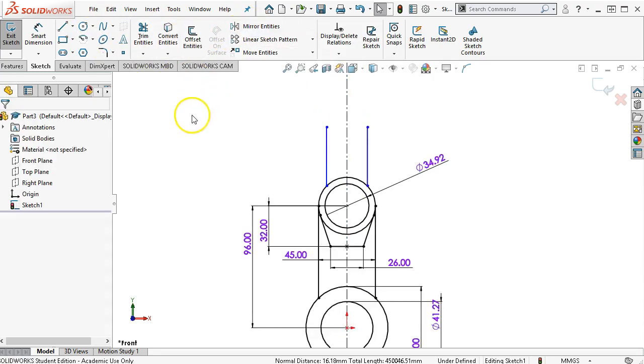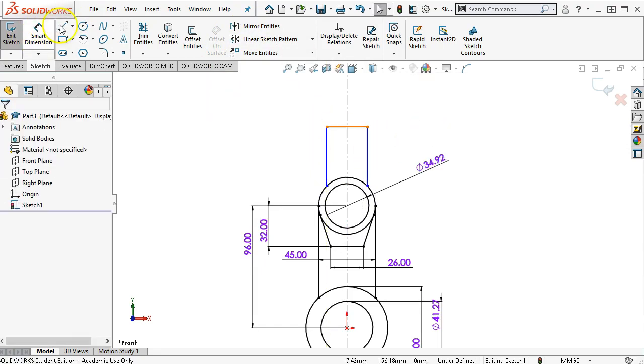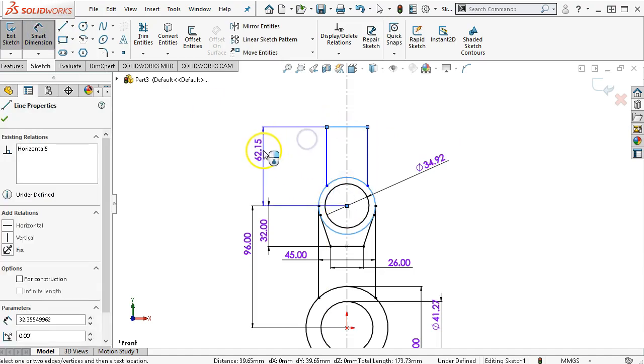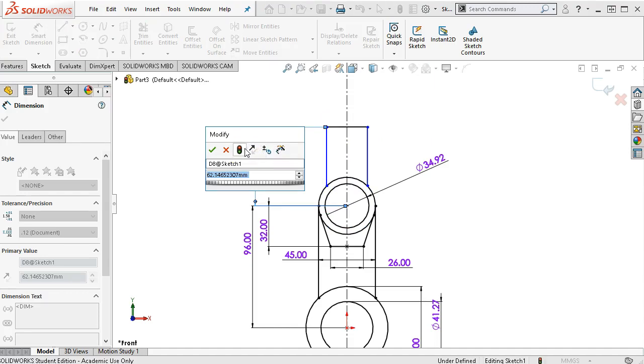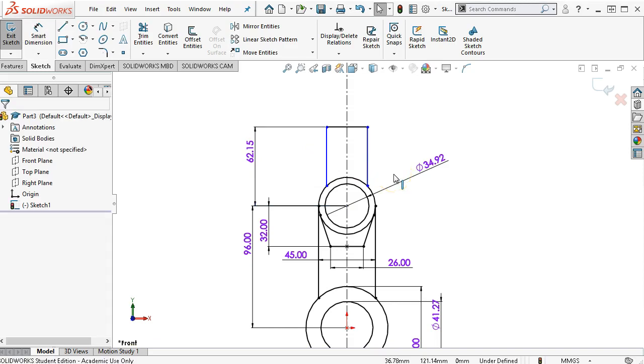So I select the object, hold down the control button, select the center line, and then pick the mirror. All right, so the overall, nope, I was thinking that one would be, all right, so one undo.